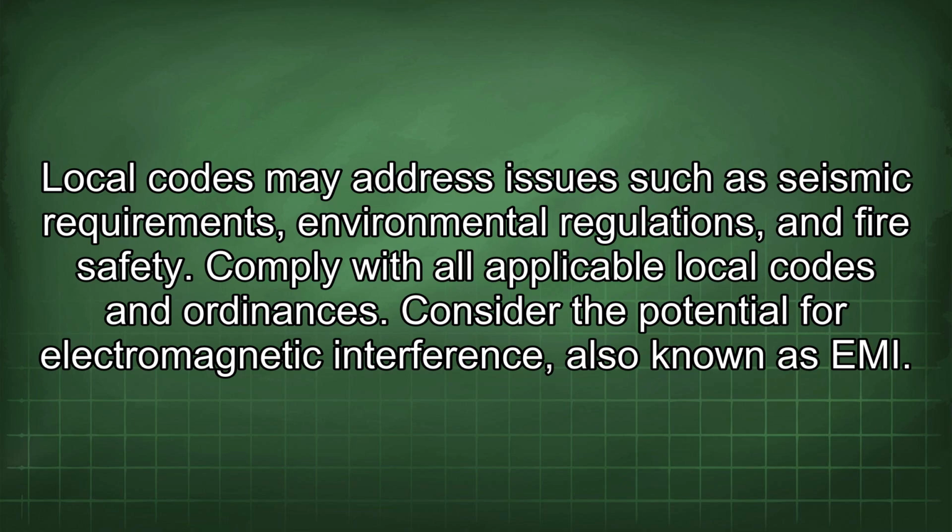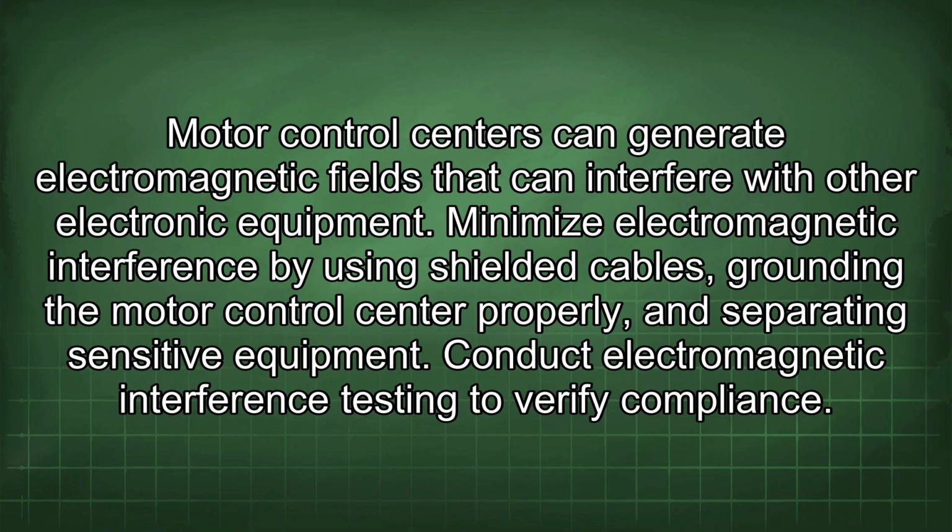Consider the potential for electromagnetic interference, also known as EMI. Motor control centers can generate electromagnetic fields that can interfere with other electronic equipment. Minimize electromagnetic interference by using shielded cables, grounding the motor control center properly, and separating sensitive equipment. Conduct electromagnetic interference testing to verify compliance.